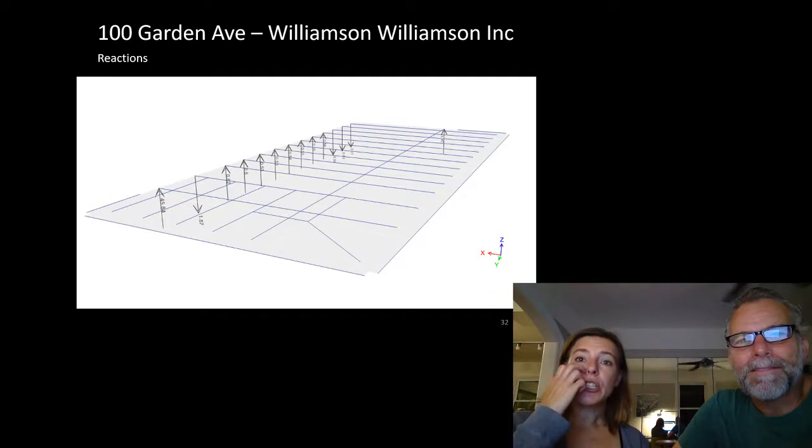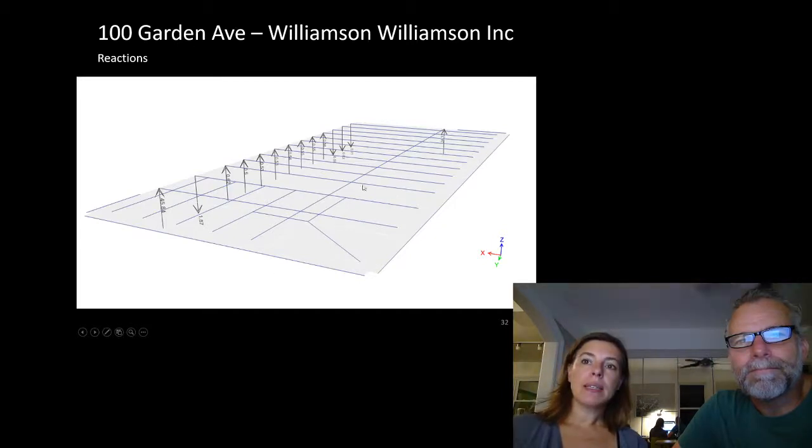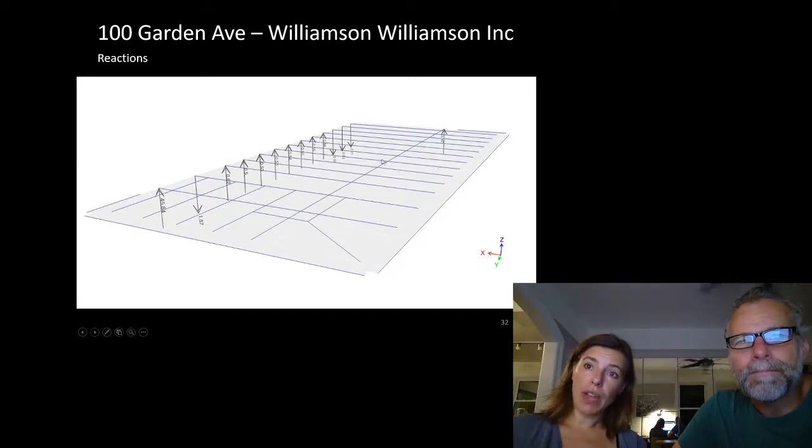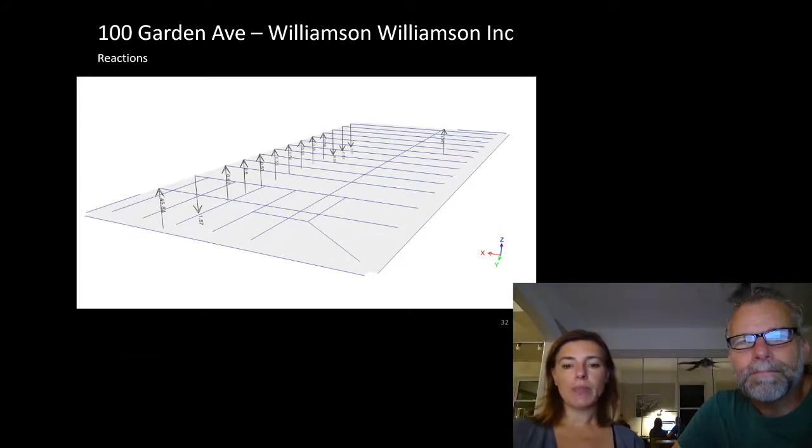So here are the reactions. You can see that it only looks like we have reactions back here. That's because what would normally be considered a reaction is actually a load that's being transferred into those major structural elements. So those had to be pulled off by looking at what the forces were in these elements, where they connected to the base building elements, and that is what I provided to the base building engineer.